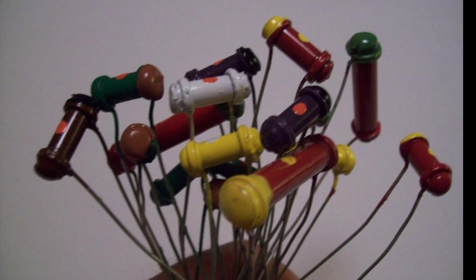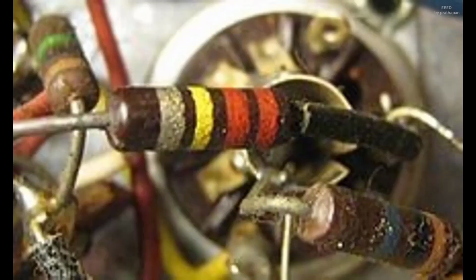The body of the resistor is protected with paint or plastic. Early 20th century carbon composition resistors had uninsulated bodies. The lead wires were wrapped around the ends of the resistance element rod and soldered. The completed resistor was painted for color coding of its value.